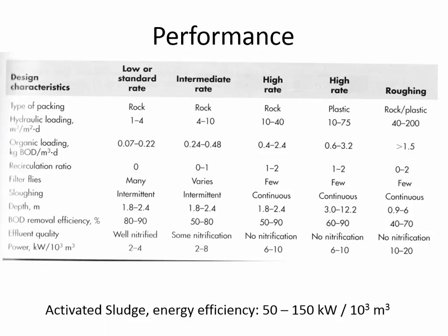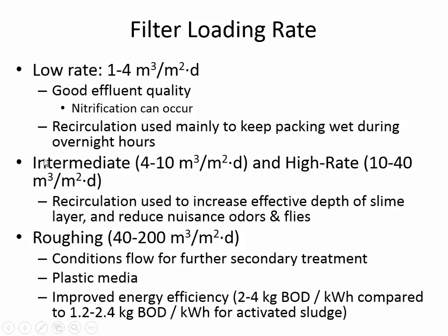In the case of organic loading rate, it's a similar thing except we're looking at the mass flow rate of BOD, kilograms per day, and then it's going to be cubic meters of volume in the filter. And so if we have a certain filter height, here's the height of the filter, then the volume would be the area times the height. And so the organic loading rate is how many kilograms per day of BOD are being loaded per volume of filter.